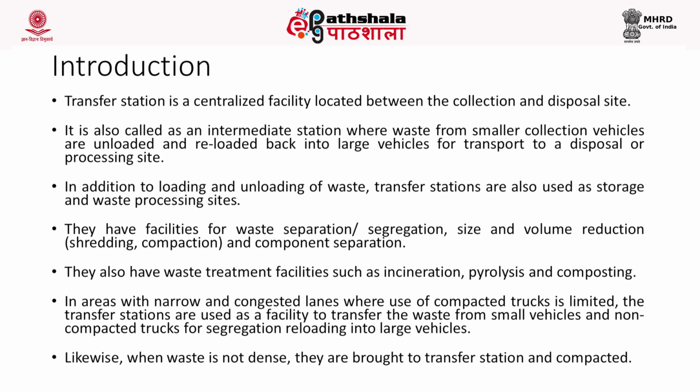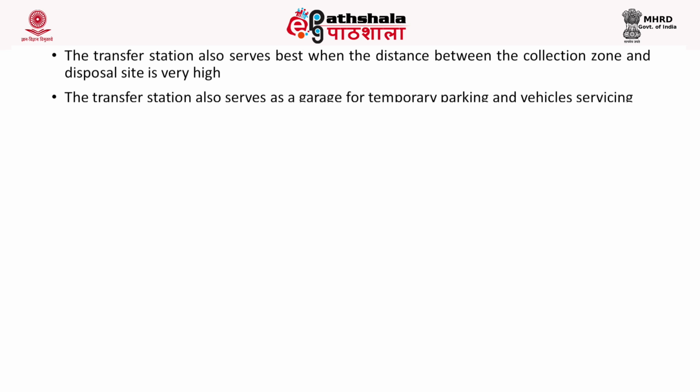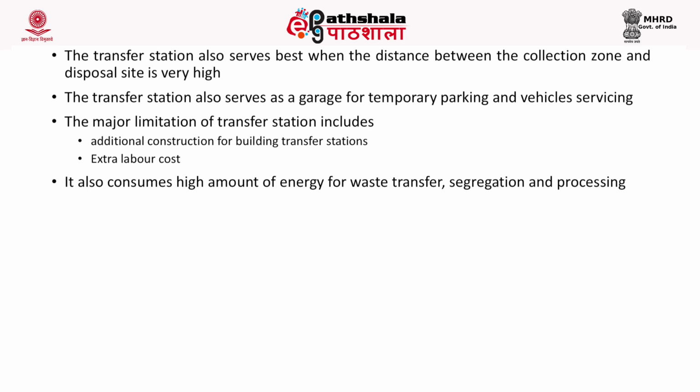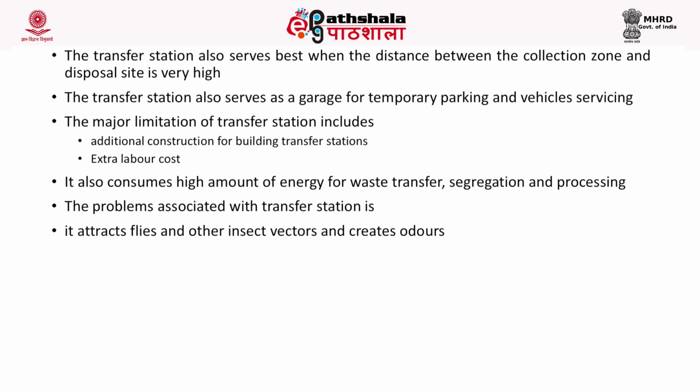Also, when the waste is not so dense, you can bring it to the transfer station and compact it. The transfer station also serves best when the distance between the collection area and the disposal site is very high. It can act as a garage for temporary parking and servicing of the collection vehicles.